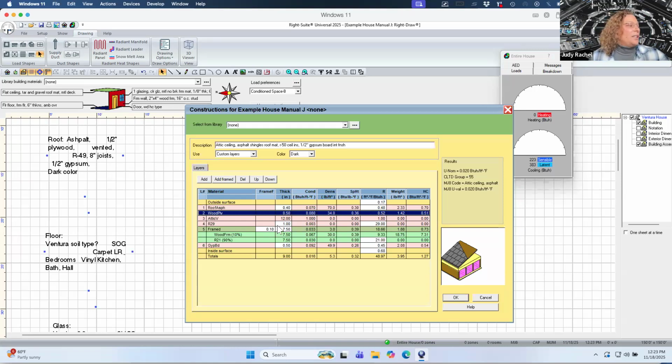The attic ventilation has a layer. Then with the insulation, the software is figuring 8-inch joists, and that does happen to be what I have in this attic, so I don't need to change that. But I would change the dimension if it was 2x6, or potentially 2x4s or 2x10s. This is what the software is saying fits between the joists, R21, and then the rest of my R49 goes above the joists.